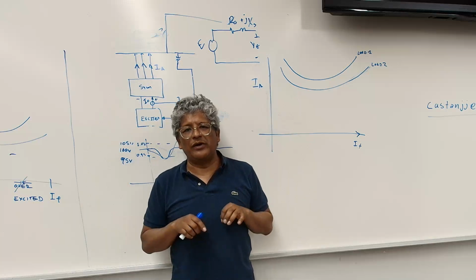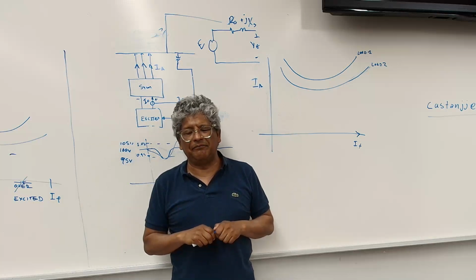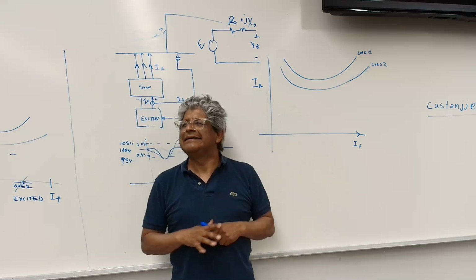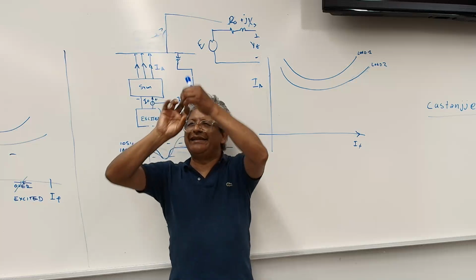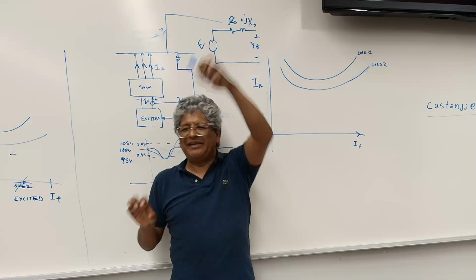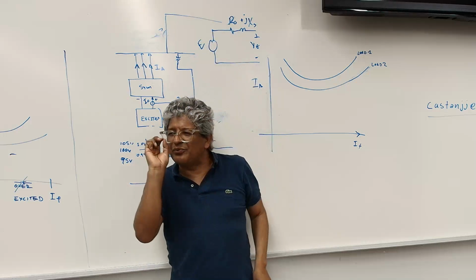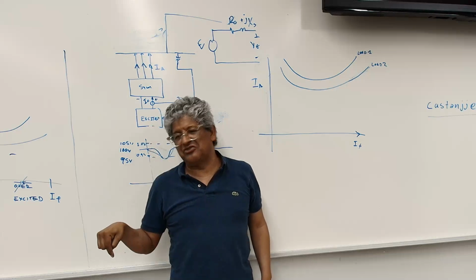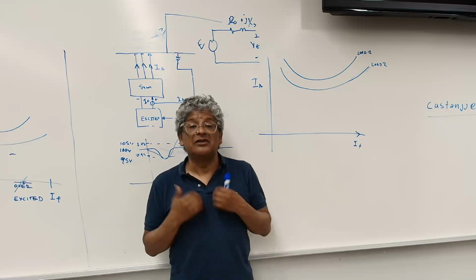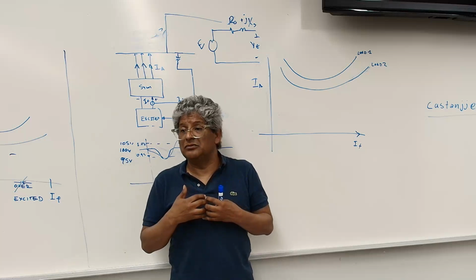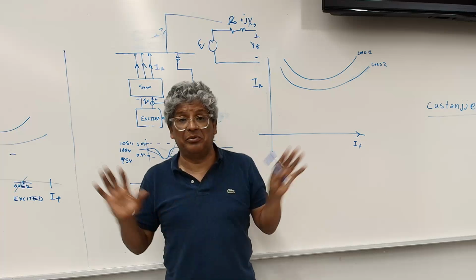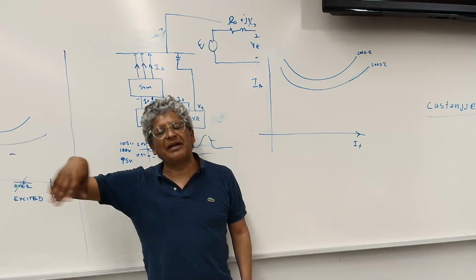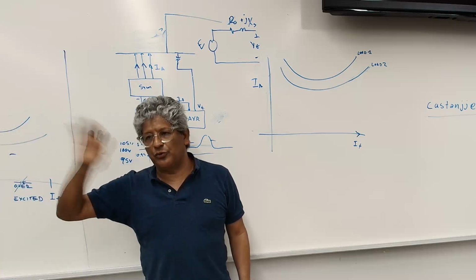So when you write the load flow equations, especially when you talk about Newton-Raphson, that's one of the methods we use in load flow, you'll see those equations and you'll see that I'm going to completely couple the real and the reactive power because basically they're connected to each other. But really what I mean is I can have big changes of real power and it doesn't make a lot of changes in my reactive power and vice versa. So that's what we say, they're lightly coupled. And in some cases we say they're completely decoupled. You can treat them as two different controllers. And we don't talk in this lab about it, but there's a separate controller for the real power.